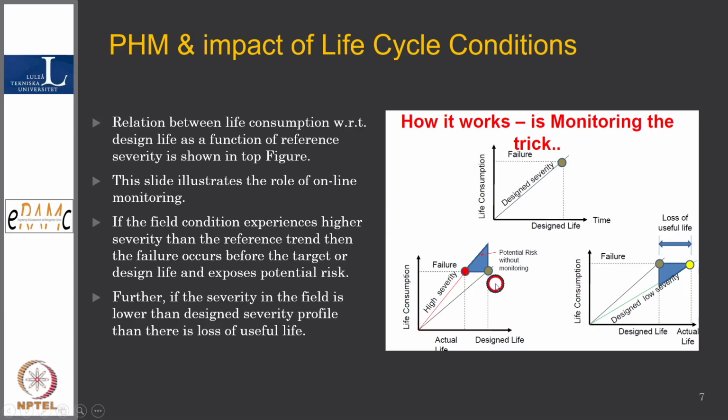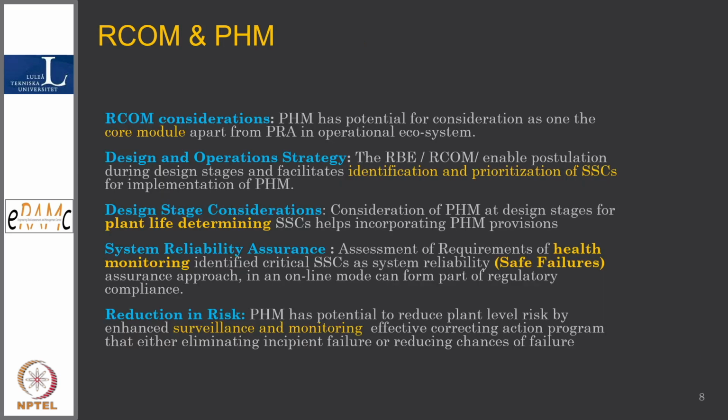But suppose I do monitoring, I will know it is up to here. Even if this situation is there, since I am monitoring, I will know that the signatures are normal and I can keep operating even beyond the design point. So this is the advantage. I think in text I am trying to tell the same thing. So it is basically bringing in the importance of online monitoring or PHM programs.